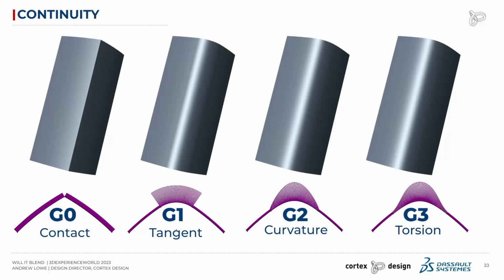Here I have an arc section. I've sketched another arc between it. That arc has a different radius than the side faces, and then there's a second or third radius between the different faces, between this face, the fillet face, and the second face. If we look at the curvature combs, there is not a smooth transition. This is the equivalent of the limo driver cranking the steering wheel, because the rate of change of this radius is constant. It has a constant curvature.